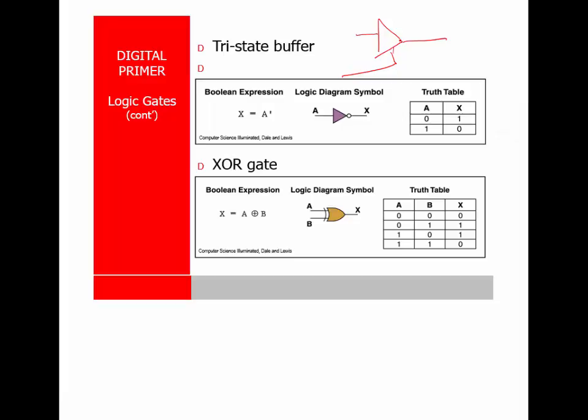This simply says that when we say tri-state, the output is either a 0, a 1, which is 0 volts or 5 volts, or a high impedance, Z. And a high impedance means that it's basically disconnected from the bus. In microprocessor circuits, we have to use a lot of tri-state buffers. They're used quite a bit, especially when we start looking at memory devices, because memory devices will have an input called output enable, and it's called different things from different manufacturers.